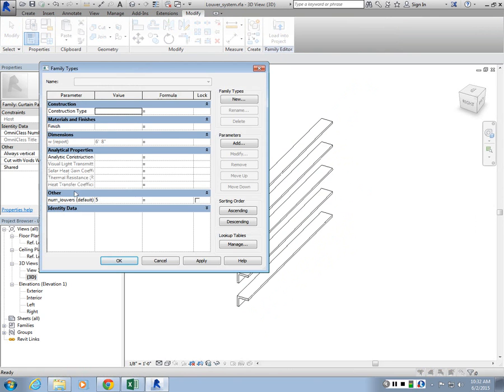So if I want to use this parameter, like I want it to be accessible to me, I need to use it in the final family that I'm creating. I need to create a parameter for it, and then link it to the parameter I want to control in the subcomponents.